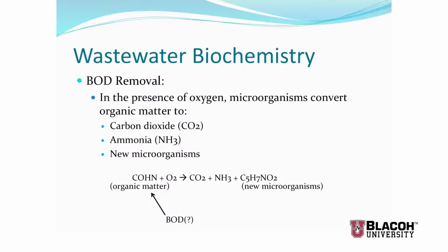You could also say, well, it is the oxygen that's being consumed by that. In the wastewater industry, they're kind of used simultaneously. And we often talk about removing BOD as if BOD were a substance. It's really a surrogate for all of this organic matter: the urine, the feces, the food products that are ground up in your disposal, and everything else that ends up in the sewer that's organic in nature and can be degraded by these microorganisms. So when we talk about removing BOD or how much BOD is in the wastewater, a lot of times the professionals are really meaning how much organic material is there that we need to get rid of. Okay.